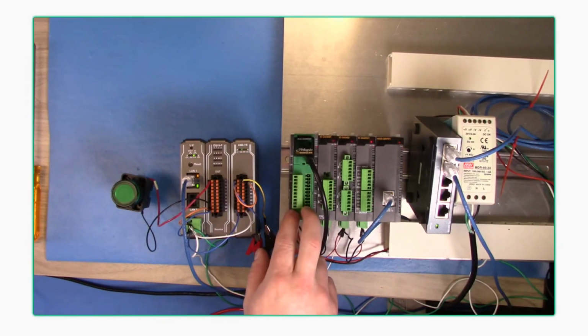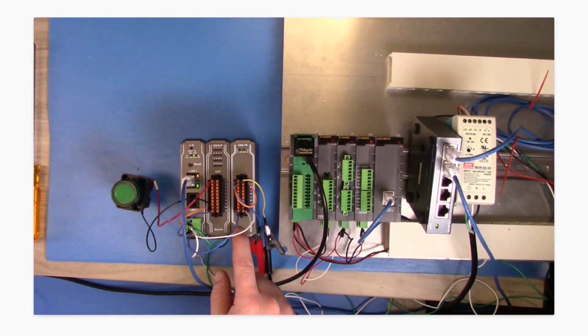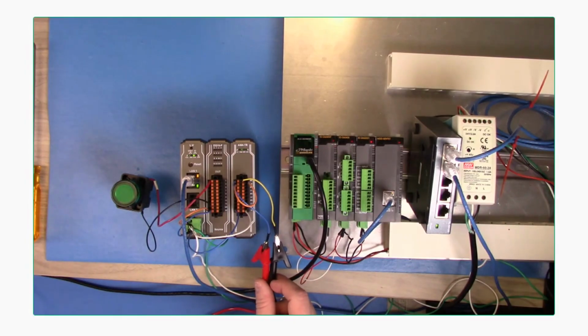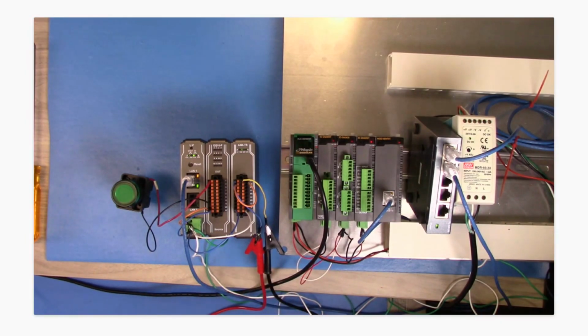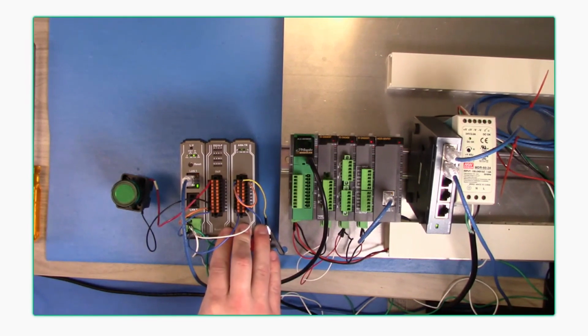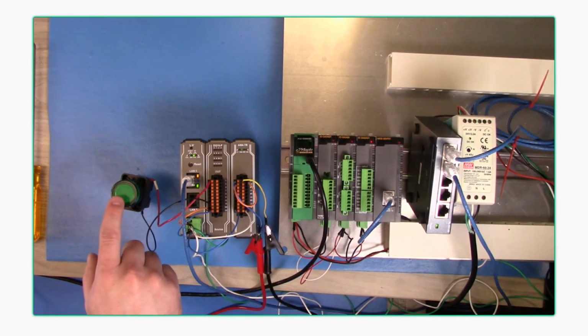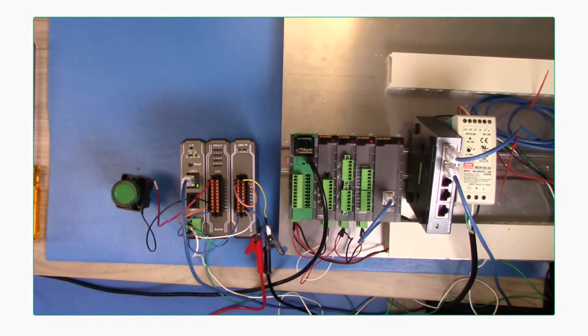We're going to have our PLC here. That's going to have all of our programming in it, and it's going to communicate to the pre-mapped internal addresses on this digital module and this analog module to read a signal. For this example, I have a signal generator wired up to analog input channel 0, and it's going to be representing a type J thermocouple. And basically what we're going to show here in a minute, once we take a look at the configuration, is how to take the addresses from these remote I/O and map them into this PLC so that we can monitor the analog input and trigger an alarm on this LED from the digital module in case our temperature goes too high. So let's go ahead and take a look at that here.